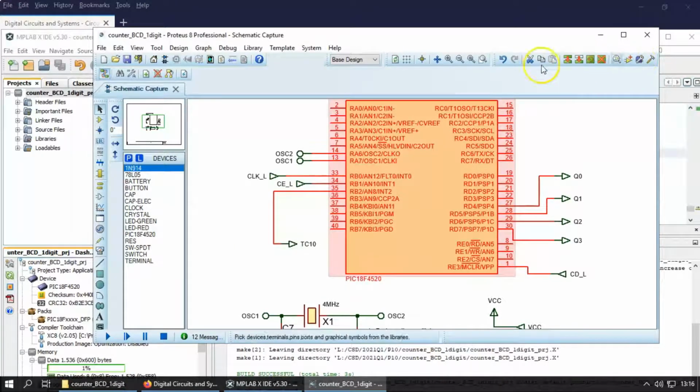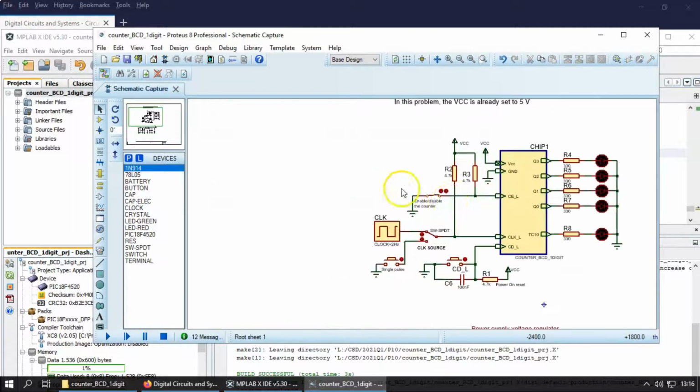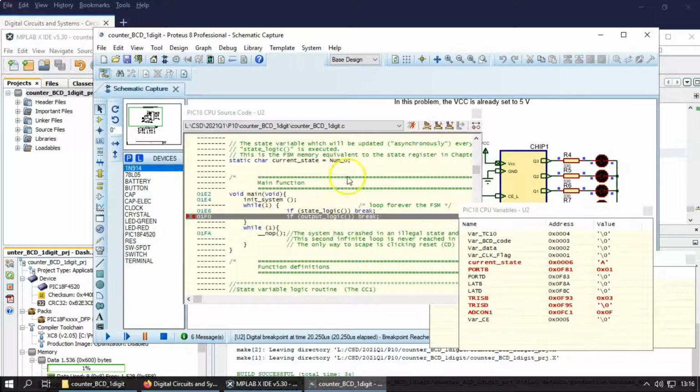So if you go to the top now, because you have changed that oscillator, it's like soldering another clock for this computer in the board. So when you run now, you happen to have the same breakpoint in the same place, but now you see the time elapsed is only 19.25, exactly 83 divided by 4, okay? Is that right?